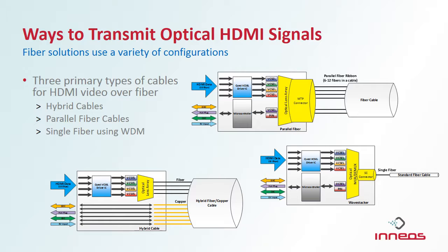This cable is cheap and easy to make, but the connection to the optics has to be done in the factory. You can't cut this cable and terminate it in the field because there's 4 fibers and then 5 or more very, very tiny copper wires that you just don't want to be terminating in the field.